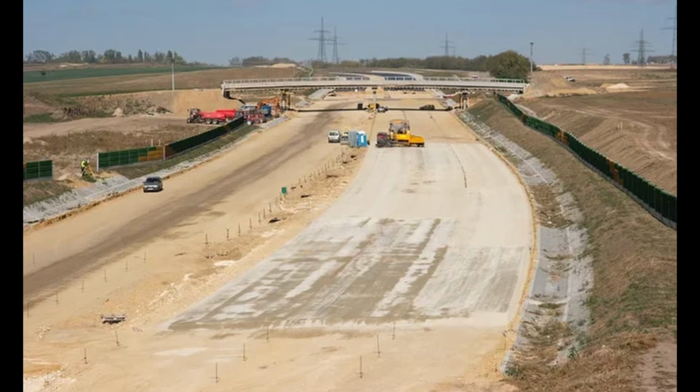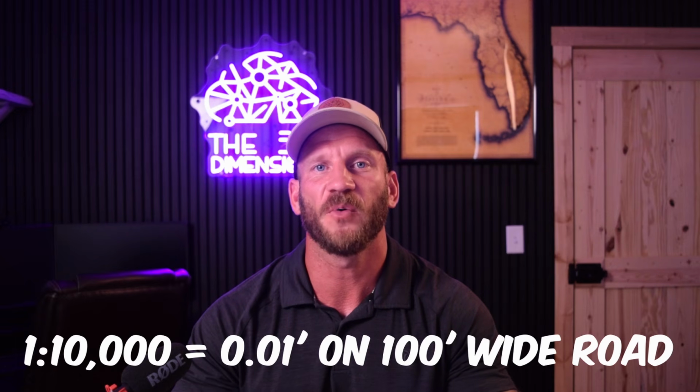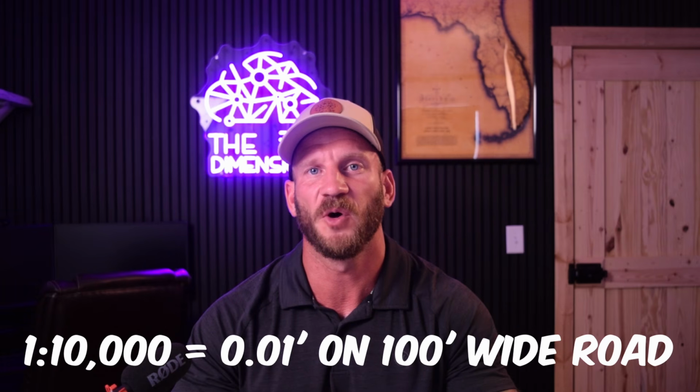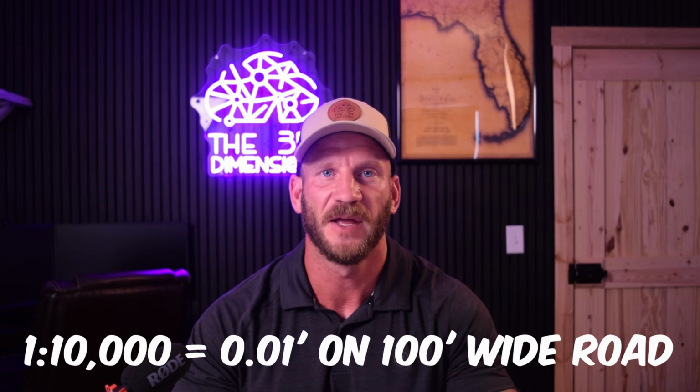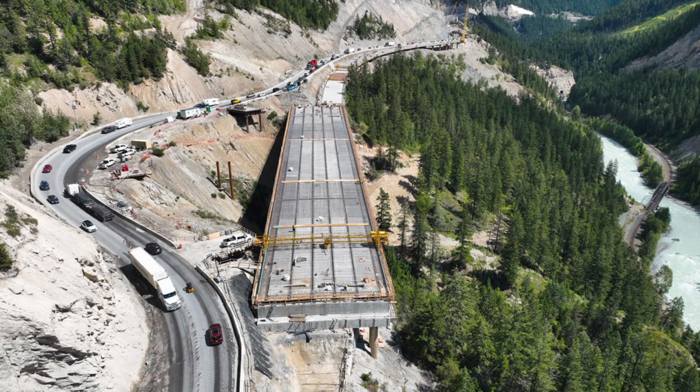One thing to keep in mind, some projects are designed using grid coordinates and should not be converted to ground. A roadway corridor project would be an example. 100 miles of road would mean numerous scale factors over a span of that distance, and there really isn't an accuracy need in that style of project where the difference between grid and ground is going to affect much. An error ratio of 1 to 10,000 is negligible when we're talking about earthworks and asphalt. Now, if that roadway came to a fairly substantial steel bridge crossing, that's where things could change. That section may be required to be designed and staked in a local ground system.